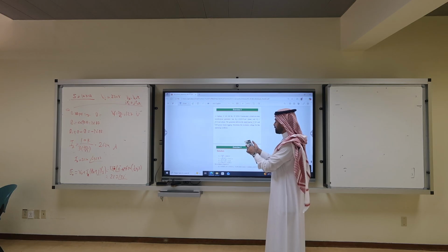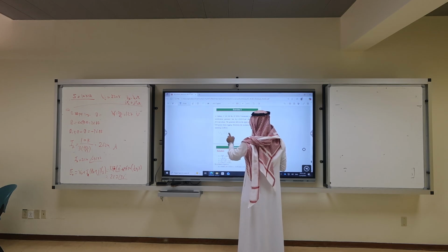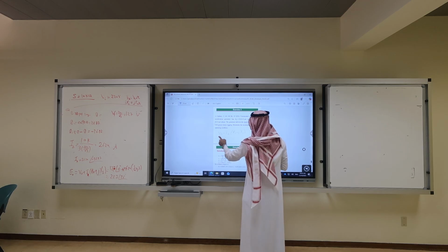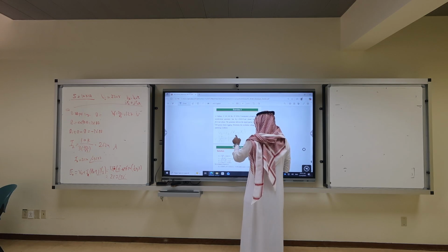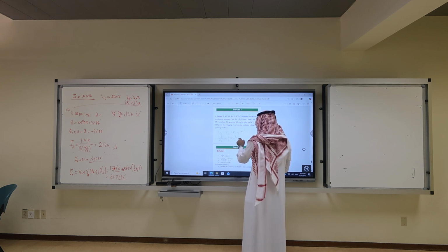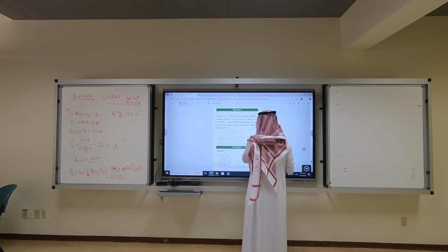So now I do the calculation. EA equals VT plus IA times RA plus JXS. So what is VT? 11 kilo over square root of 3, plus what is the IA? 1312 angle shift cosine 0.85. What is shift cosine 0.85? It is 32, it will be minus 32. Why? Because theta is positive 32, this is minus 32. No, not 31.78. For an angle it matters. So yes, it's very important.